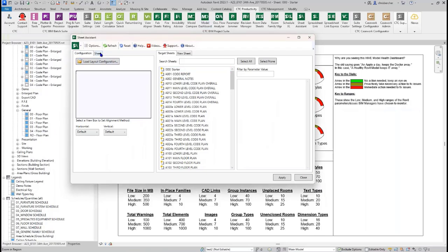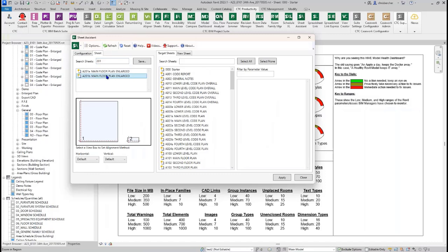And so what you get to do is set up a layout, and you could specify a target sheet to build it off of, and specify what the alignment properties of that target, those views are: bottom right, top right, bottom left, top left, center, middle, whatever you want. You can set that, you can save it as its own little config file. It can be a floor plan, a schedule, a legend, a detail or details, your generic annotations, keynote schedule, what have you, right?